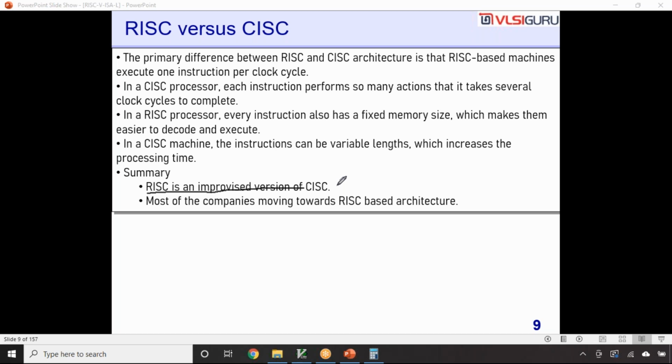The people who developed RISC architecture in the 1980s developed it to address these drawbacks. So what were the drawbacks in the CISC processor? For each instruction, you don't know for sure how many clock cycles it takes, and we don't even know the size of each instruction. To address that problem, they broke down those complex instructions into small, efficient instructions.